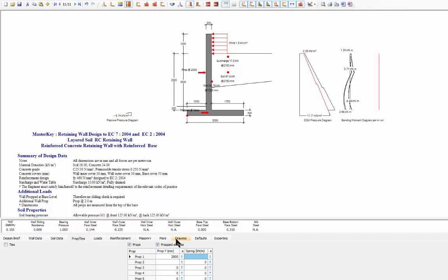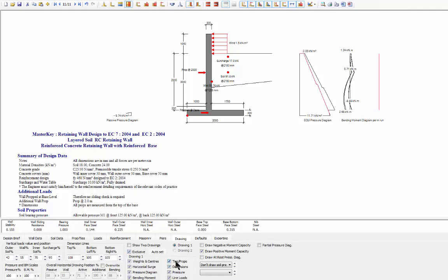And if I just go to my drawing and I knock off the moment capacities, we get an enlarged applied moment diagram. We can see this effect of this prop here coming up, and you'll wonder, why is it starting not at 0? The simple answer is, from a soil point of view, that's the load, except we have this external load of 1.5 at 525 mil up is giving us our factored or unfactored overturning moment. So we've got a pre-existing moment from the wind load coming through into the frame.